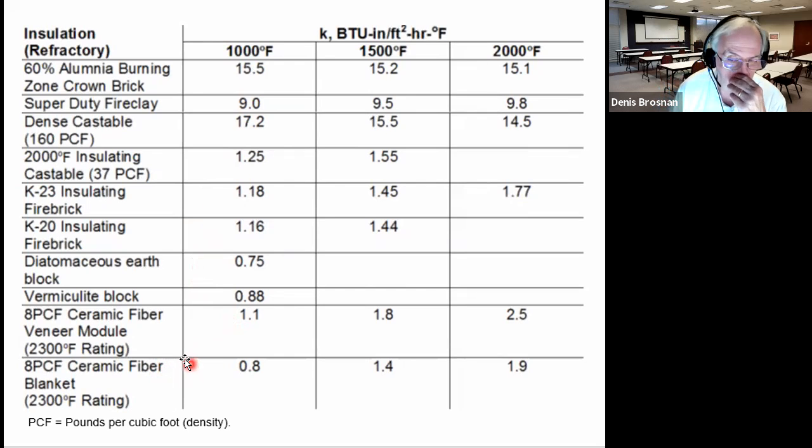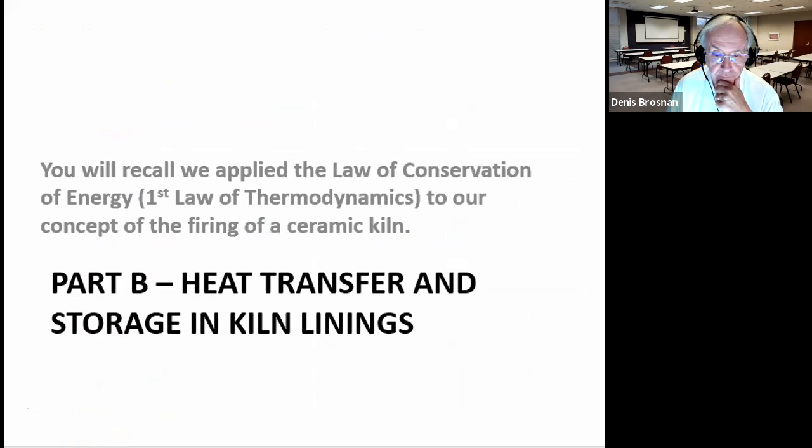So just trying to make the connection that as you go more porous, you're losing strength, ruggedness, durability. So for a hearth, you might have to have material up here, but for just pure insulation, you might come down into this area right here. Now we're going to do some calculations in a little bit, which we're going to talk about ceramic fiber and blanket products.